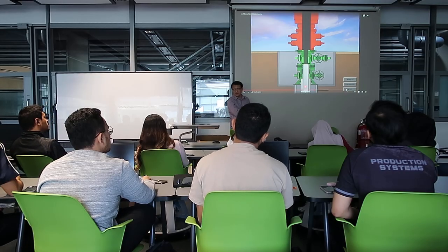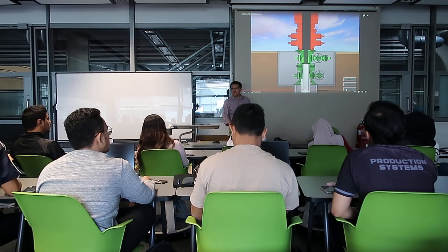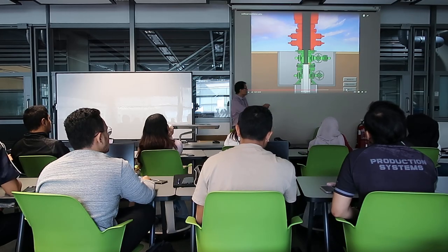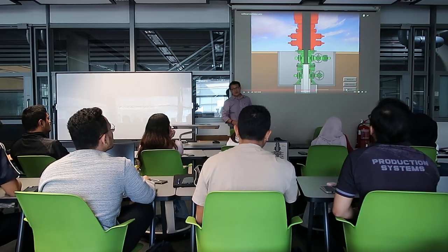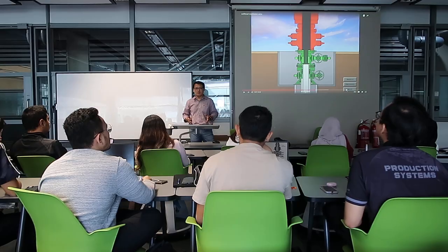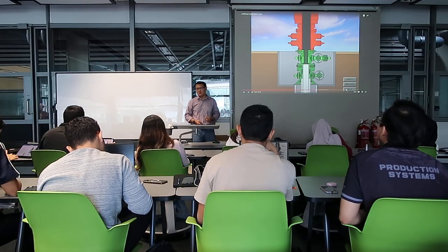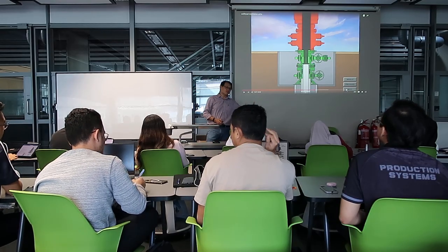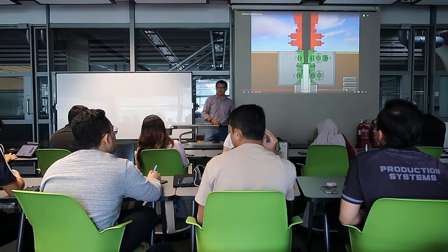At that stage, I already know whether this hanger is sealing or not. So when this hanger is sealing, I remove one possible cause. So when you put this wellhead on top, if it's filled, it's only this seal that will leak, because here you already verified. So all this testing time, we are talking about maybe 15 minutes, half an hour. But it does help you to actually go back to the first stage. Because if we want to redo everything, it's NPT hours, probably a couple of hours.